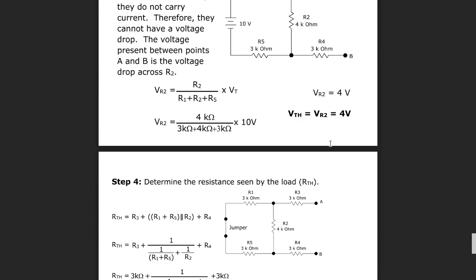We can find its equivalent in a single resistor, which is all of the resistance that is given to that R load. If we take R load, the resistance of the load, equal to that equivalent resistance which all of the circuit is delivering to it, we can have maximum power.